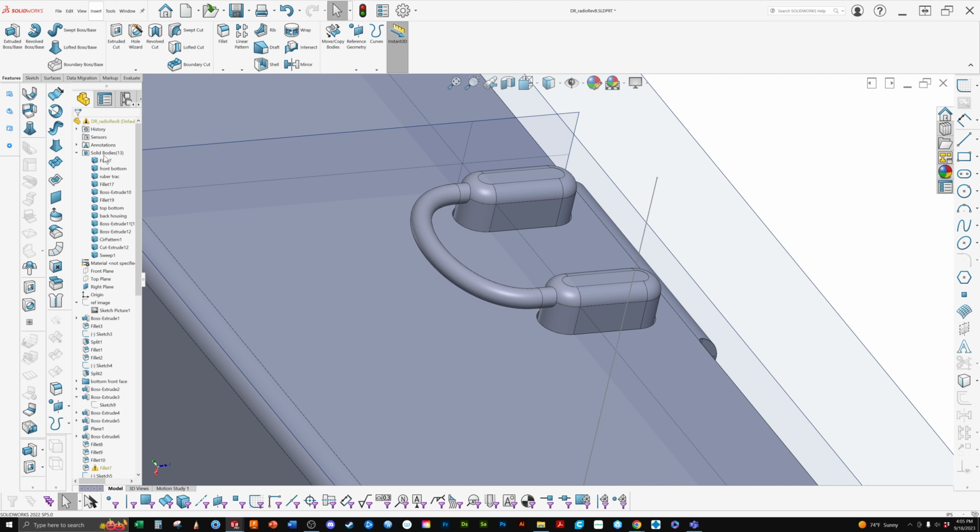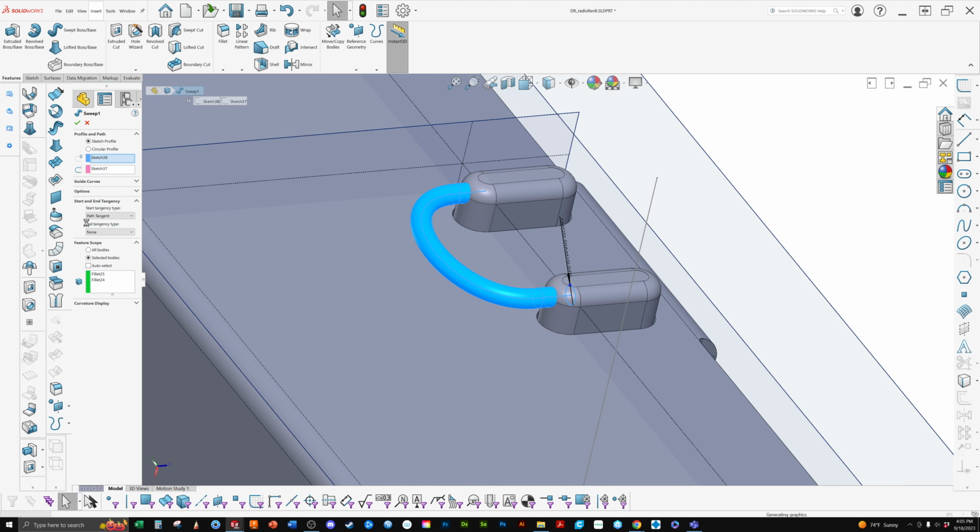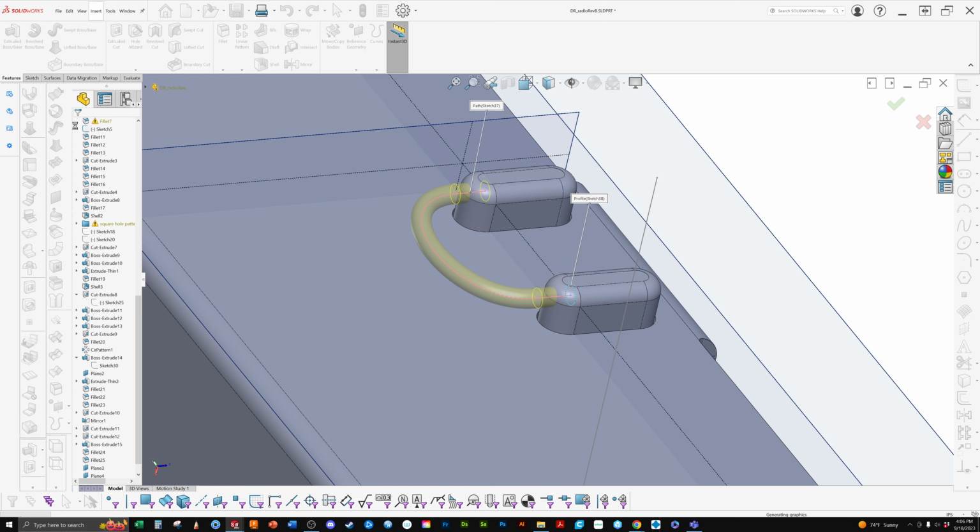Nope. What's going on there? Oh, there we go. So for some reason, we've always seen on the extrude boss command that merge features is always showing. So for here, we've got to go under our options and turn off merge results. So now we have that separate object.